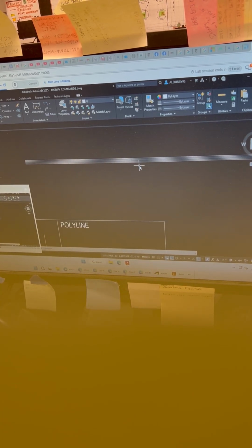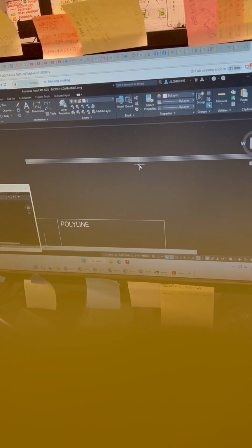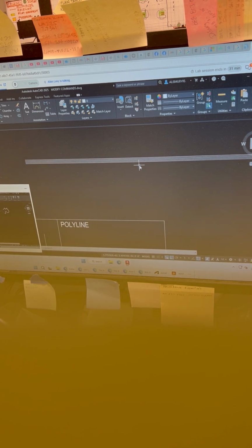That might be difficult, but here's the thing. You do not have to be anywhere near anything to offset. You can be so far away and still click, and it'll still offset the same. Okay? Like, for instance, if I select this bottom line, I don't have to be this close by. Now, I'm exaggerating this, and of course it would be less efficient to do something like this. You don't need to do this. But it'll still work is what I'm getting at.